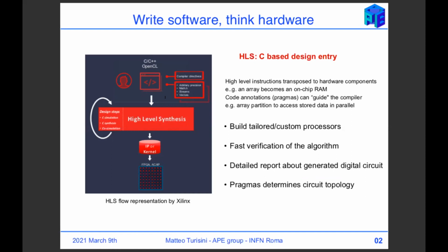on the chip. And the nice part of this C front end is that you can have a fast verification of your algorithm, test its functionality, and then analyze the report generated by the high-level synthesis tool to understand how the functionality has been implemented on the FPGA, and then you can iterate in order to have the optimal design you want. It can be very high throughput, it can be low latency design, or it can be both.